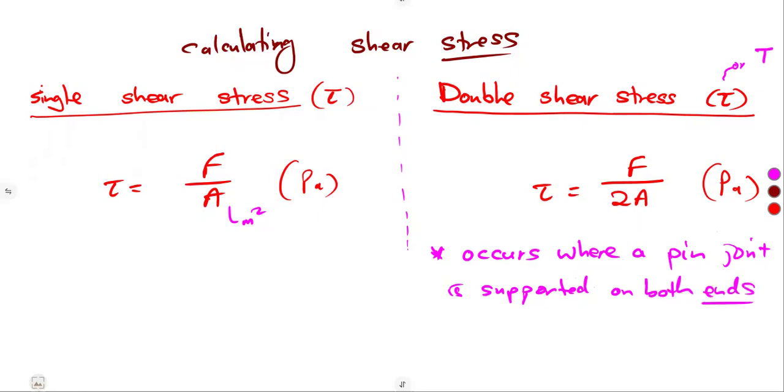So that is where we consider the clevis and hook, the major part that we are going to see. If they say we are given a clevis clip, you know that you are dealing with a double shear stress there. Double shear stress. So that is it, guys.